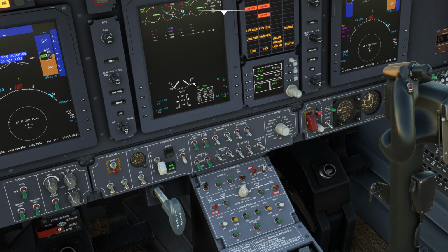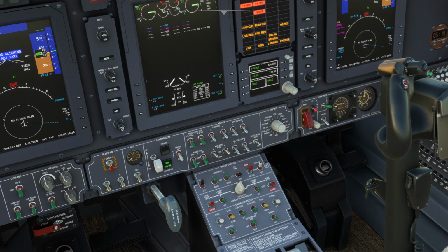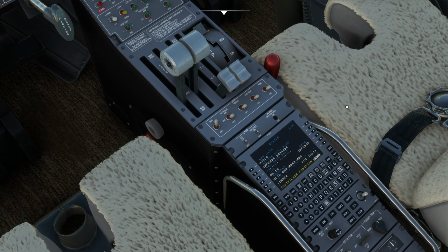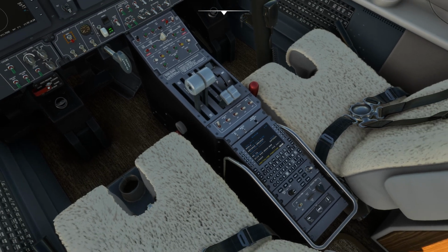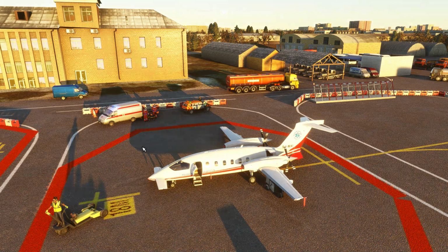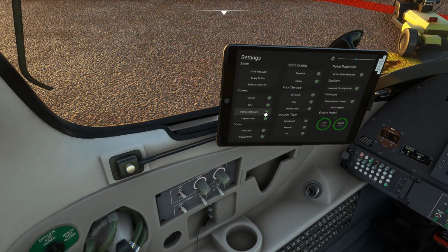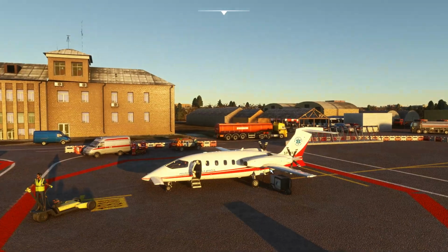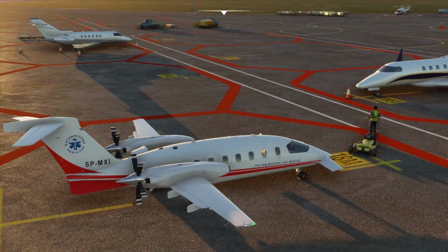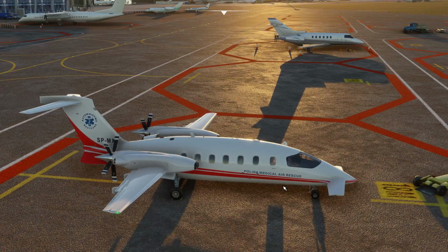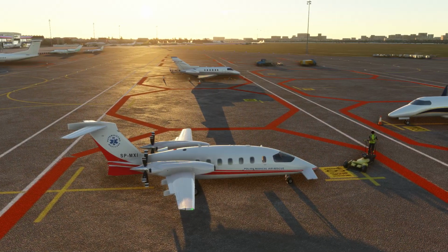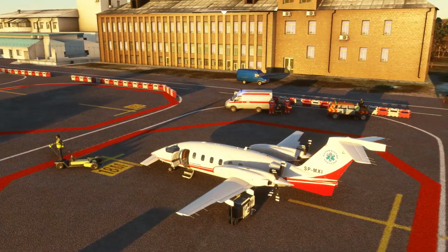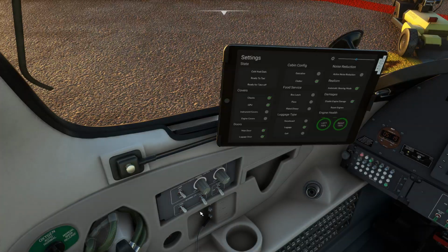External power message on MFD, we do have it. Cabin and aircraft lights in illumination, we do have it, and position lights on. We are doing things in the cockpit, so your position lights need to be on at the same time. Instrument covers, engine covers should already be off, so the ground crew, whoever they are, whatever aircraft they're moving around, they can see our position lights, and they can be cautious.